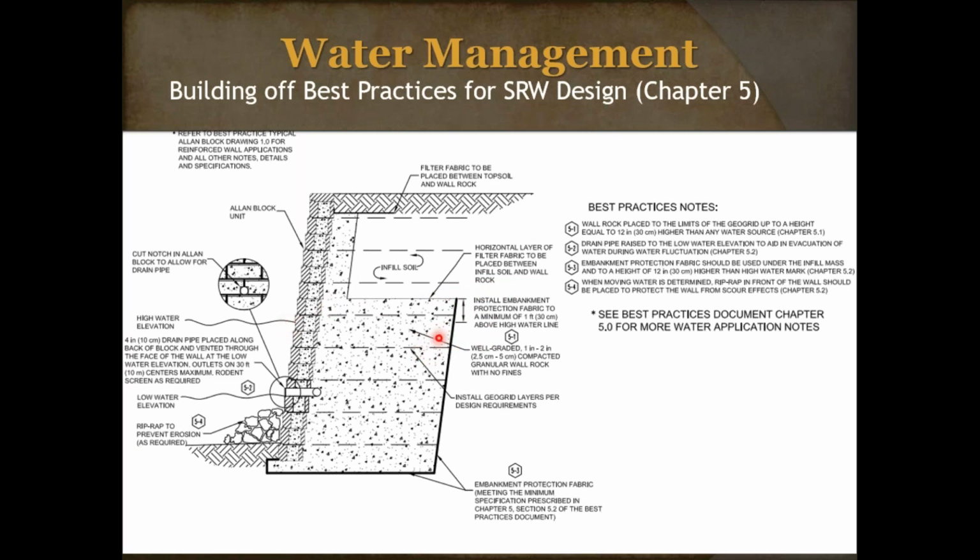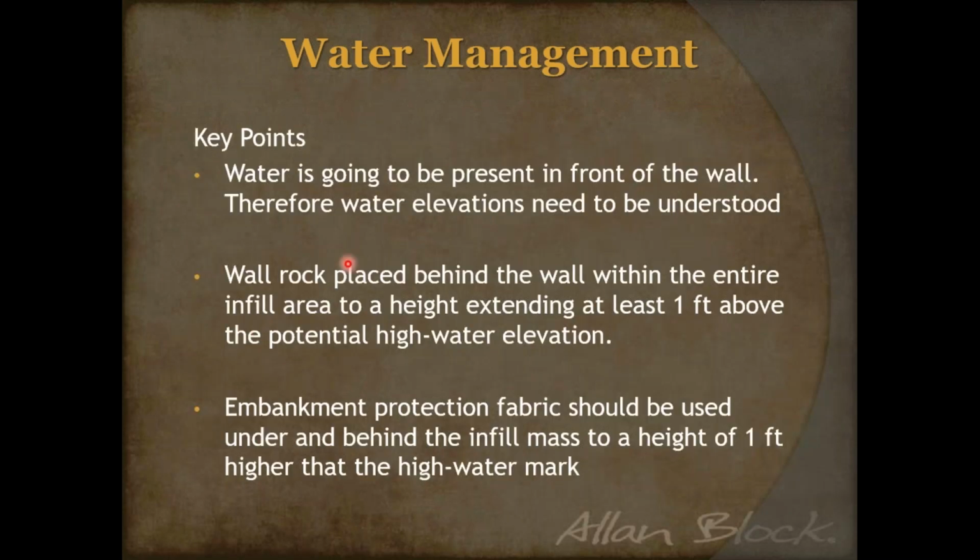Yes, we see guys go all the way up. Yes, we see guys take that fabric and go horizontally so that way this material doesn't fall into this. But the critical element for me is making sure you get the little extra redundancy that you're 1 foot higher than whatever that high water mark is. All right? And that's really what we're pointing out with the bioretention.